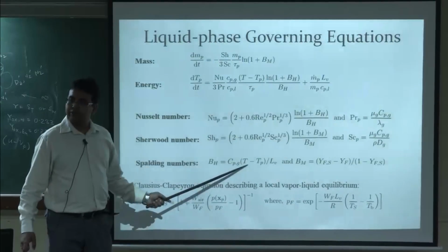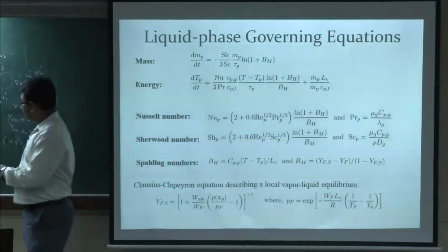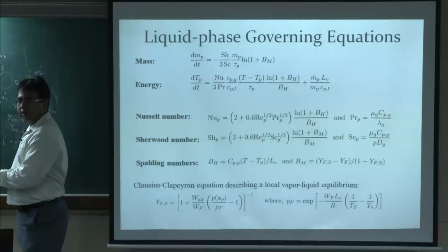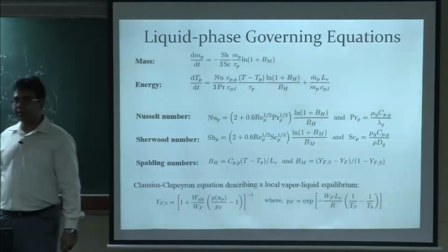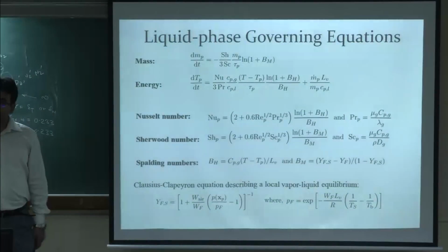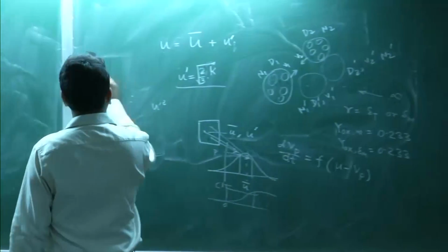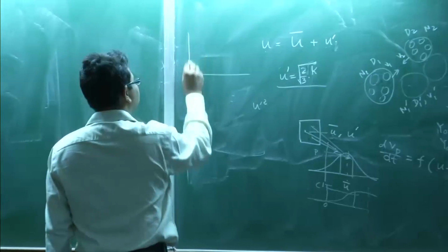So, ideally you should use the instantaneous temperature. Like here we have used the instantaneous velocity. Similarly, we should recover instantaneous temperature from the mean temperature somehow. So, what we can do, we basically know the mixture fraction and variance, right.